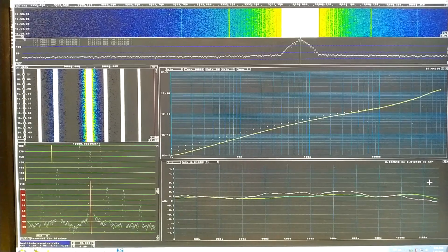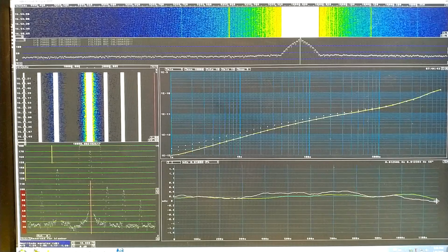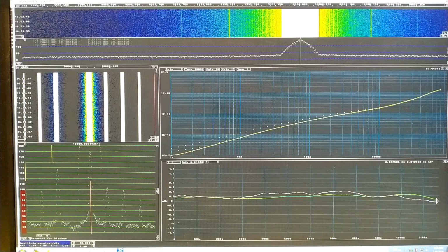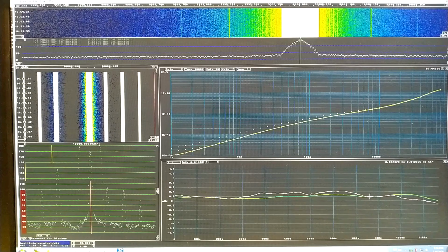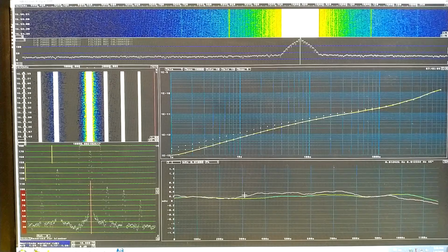And here is frequency versus time. It is hard to see much correlation between red and green, except here at the end when I entered the room, because I moved the air around the box and changed the temperature just by coming here. But the green trace, that is the Wenzel oscillator, mixed with my device under test. And it's clear I need a better oscillator for channel 2 that will make convergence faster when I do these